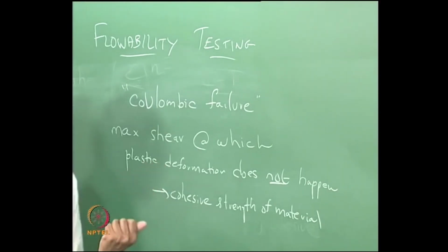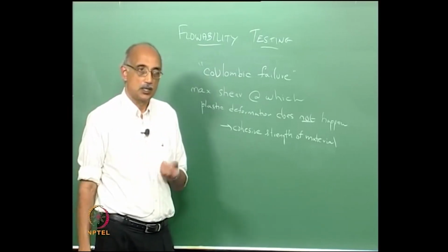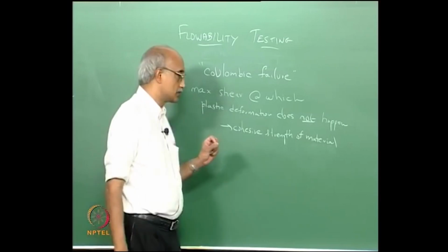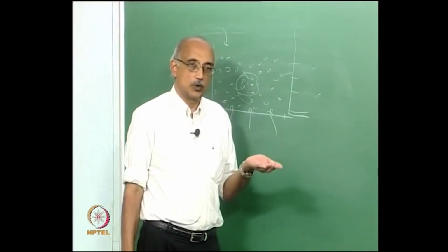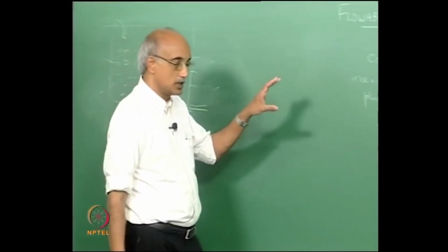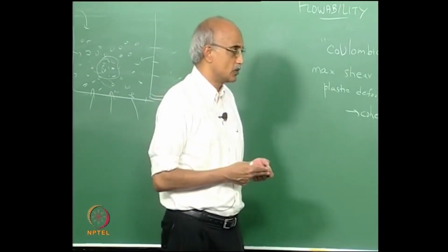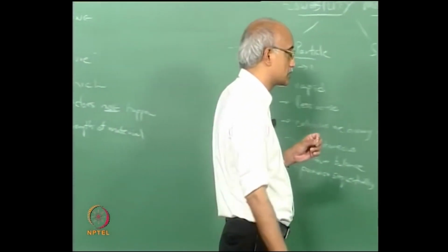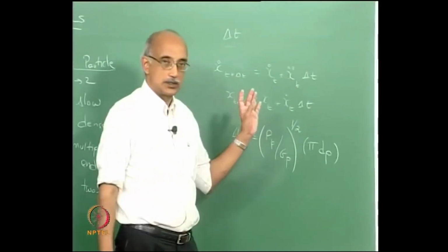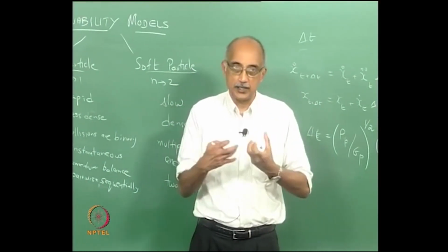And so, what this requires is the use of shear testers. You have to apply shear stress and look for deformation characteristics. And again, that is where the problem comes in. It is fairly convenient to apply these shear stresses on the outsides and look at the induced flow, but it is very difficult to apply these shear forces in the interior or center or bulk of the material and note the induced flow characteristics. So, what that has made happen is that there is increasing dependence on coming up with accurate models that can predict how a mass of material will behave when it's packed together tightly.